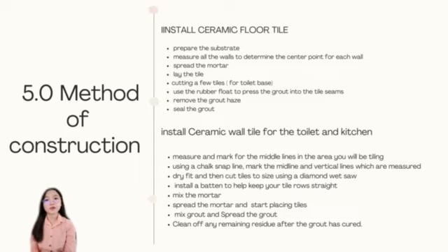These are for the toilet base. And next, use the rubber float to place the grout into the tile seams. The next step, remove the grout haze, and the last step is seal the grout.